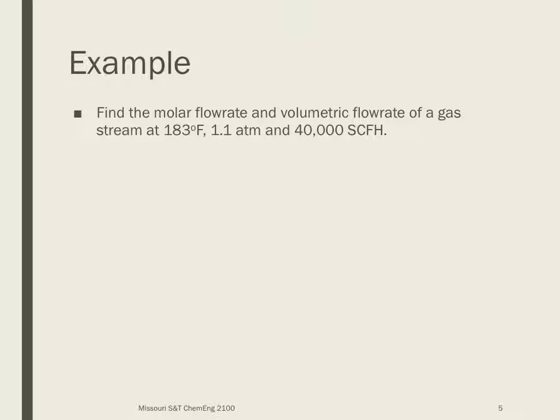We have in this case a gas stream that's flowing at 183 degrees Fahrenheit, 1.1 atmosphere, and 40,000 SCFH. And we want to find the molar flow rate and the volumetric flow rate of this gas. Now, in this particular case, SCFH is most closely related to the mass, or the molar flow rate.